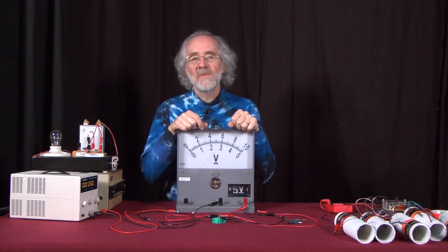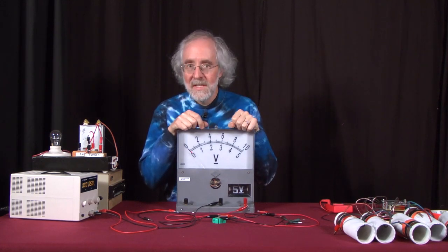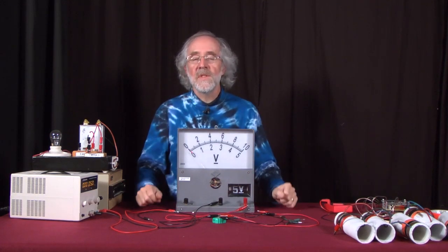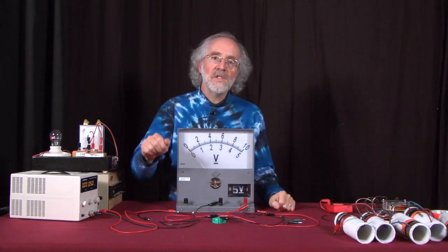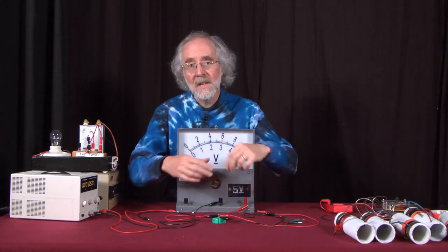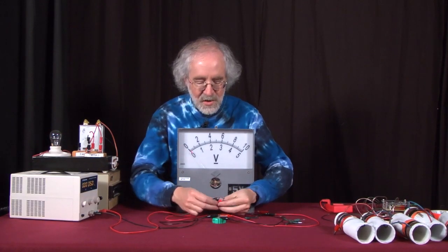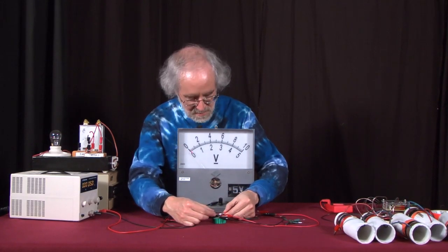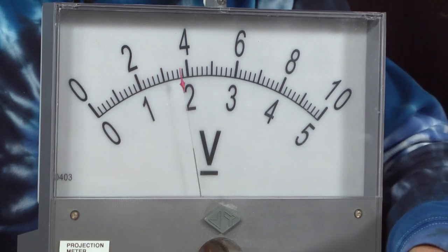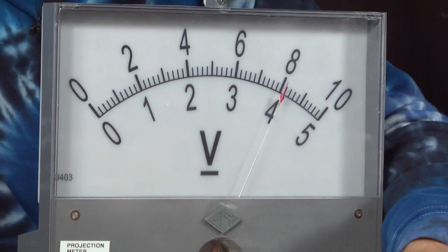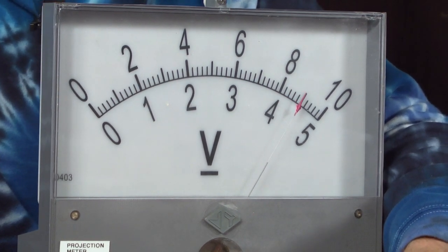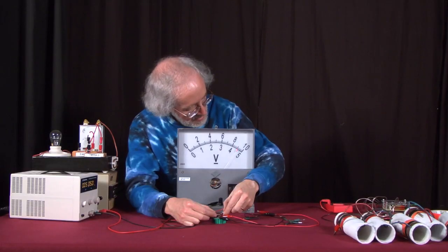In the final part of chapter 23, we're going to introduce capacitors into circuits. We're going to start with a simple circuit that consists of a capacitor and a resistor, specifically a light bulb. So I'll take this capacitor right here, and I'll charge it up to about 5 volts. When I hook it up to the power supply, you can see it takes some time to charge up. And it's charged up to just about 5 volts.